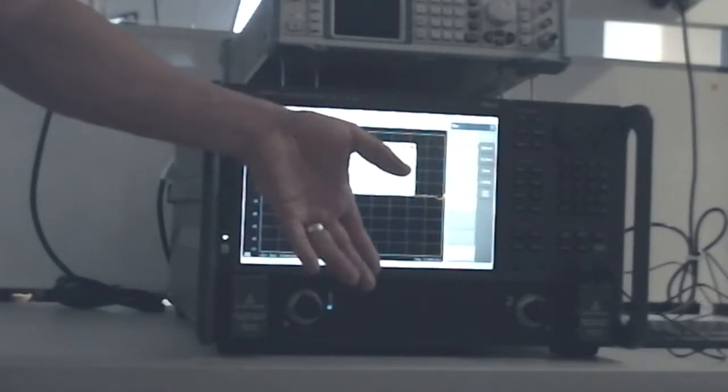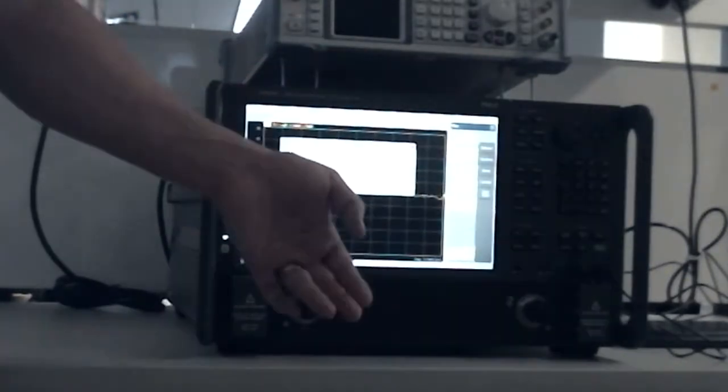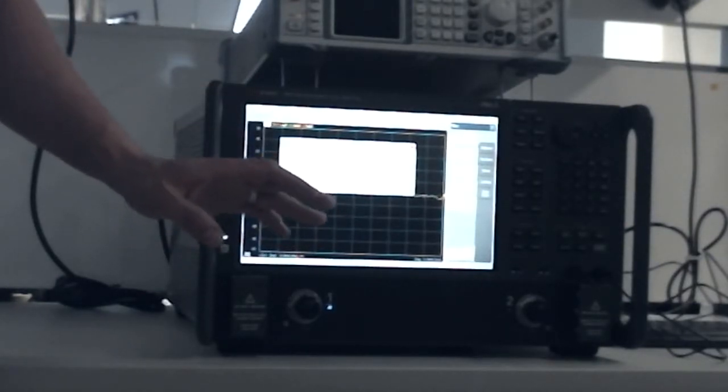So if you're looking at antennas, right? Sorry, you had a question? Just say it's one port. Yeah. So antennas are typically one port unless they're differential, in which case two port. And you can do a differential return loss measurement with a two port, right? Because now you have your positive and negative on your differential, and you can just still do your two port balanced topology. Now, do you guys ever build differential antennas, or is it mostly single-ended antennas? Just single. Single-ended? Okay. I'll show you guys how to do it.